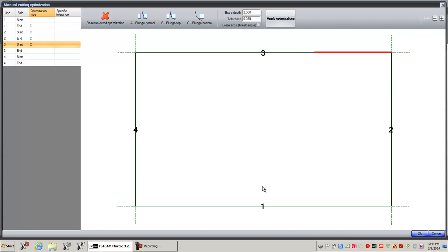That's all I need. Extra depth is going to go 2.5 inches down. Now again, this depends on the diameter of the blade. Remember, you have the blade, and then there are 2 flanges that sandwich the blade onto the arbor of the motor. I'm going to explain tolerance later.